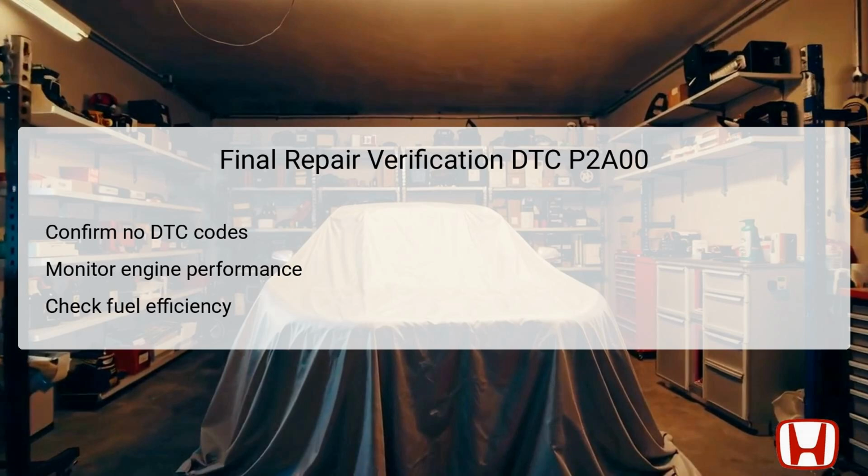It's also important to note any improvements in fuel efficiency, as a correct air-fuel mixture should yield better fuel economy. Conduct a test drive under various conditions to confirm that the vehicle responds correctly without triggering any warning lights or error codes. This step is critical for restoring driver confidence in the vehicle's performance and ensuring that the repairs have resolved the underlying issues effectively.